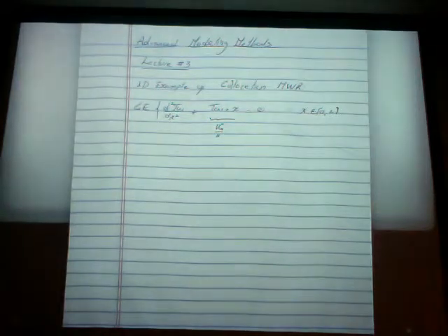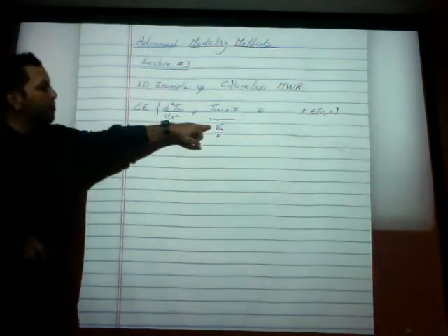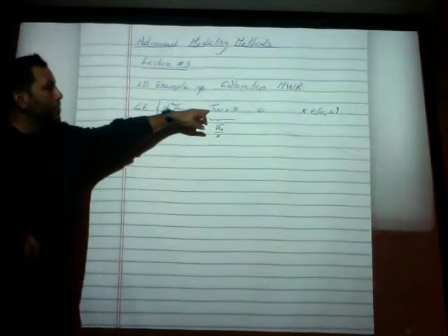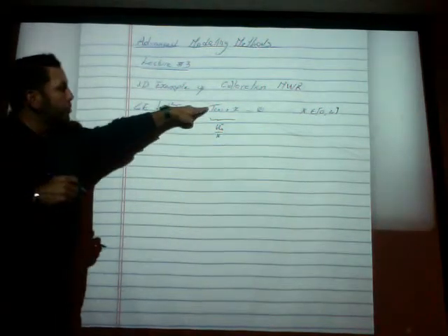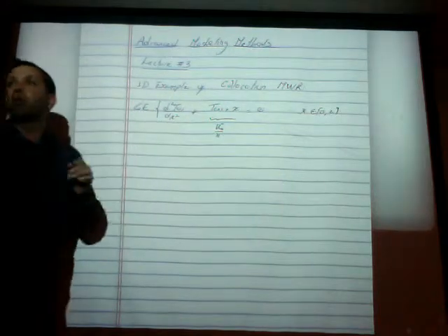So now you can see that the generation term, to make the problem a little bit more difficult, instead of being a constant, we made it a function of temperature and a function of position. Okay? So we have a bar that is L long, and so the bar has an internal energy generation, maybe due to an electrical resistance or some sort of reaction going on inside the material, which produces energy that's proportional to the temperature and proportional to the position as it goes in the L and the X direction. Okay, this is just again an analytical problem.